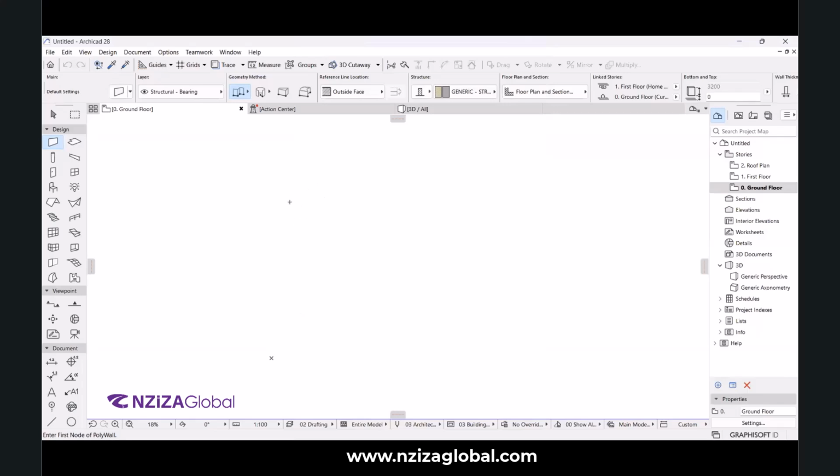Once that is done, we'll click somewhere here. As you can see, it is going this way. So we'll come up here and we'll select rectangular. Then we can go this way and I will click 8,000, which means 8 meters by 5,000, which means 5 meters.